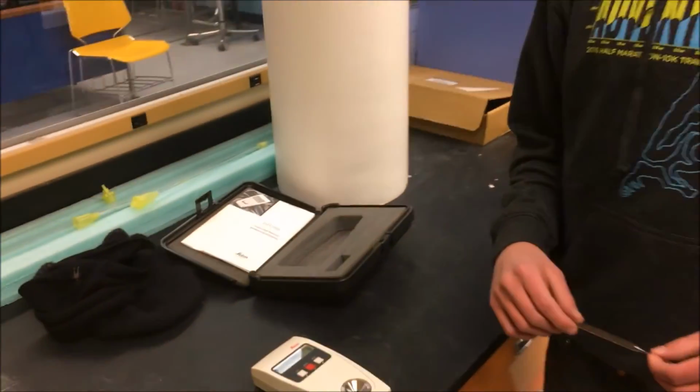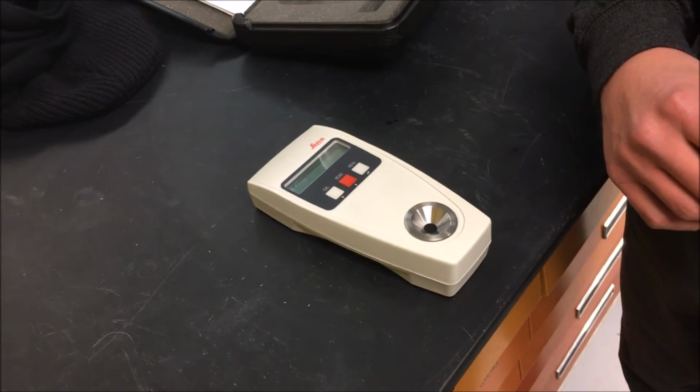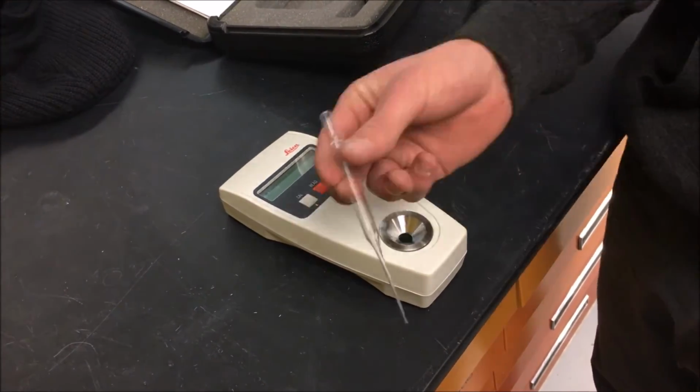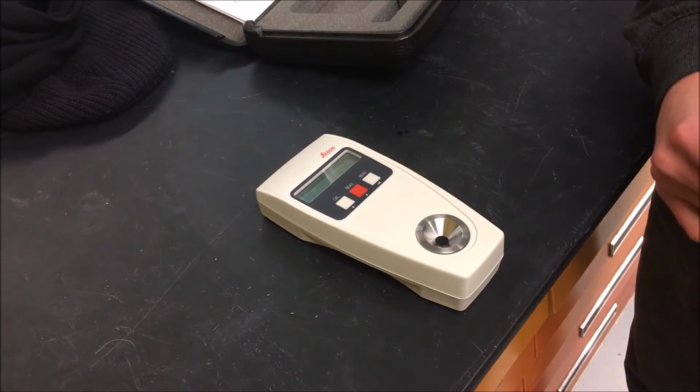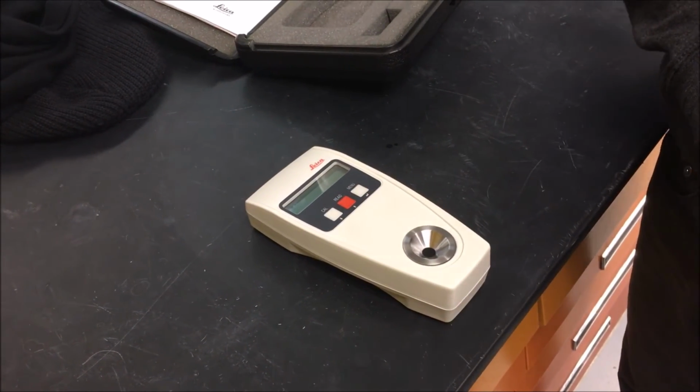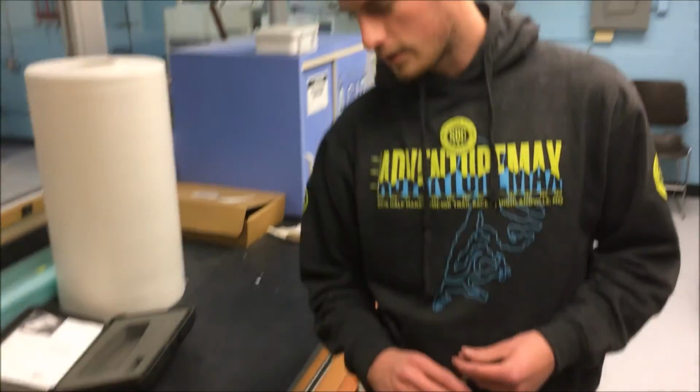Additionally, along with the mass distribution results, we used a digital refractometer to measure the optical density, or the concentration of the solution at each sieving layer. Depending on the runtime and the surface area of the distribution, you put the sieving layers in an aqueous solution, extract it using the pipette, and stick it onto this surface right here, then push read, and that measures the optical density. What we found from the results, as explained later by Matt, is that the concentration increases with a longer runtime due to the leaching process that we observed.